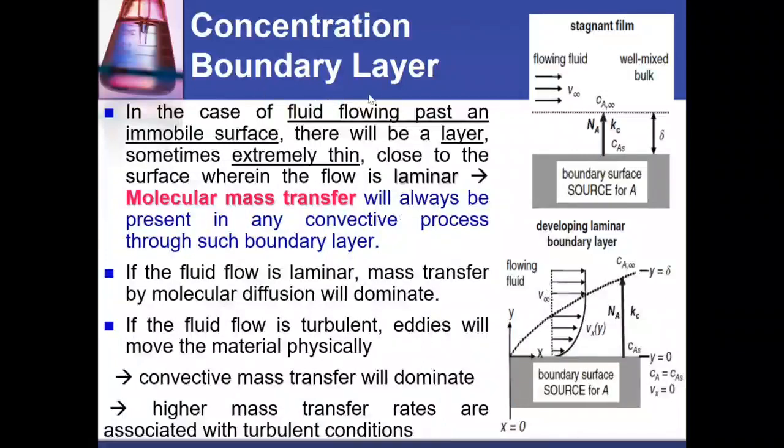So the boundary layer means that when you have solid and fluid in contact, you will have a layer of liquid here that is immobile, same as the surface, and this will affect the movement of all other molecules above them until you reach the center line. In other words, there will be a velocity gradient because of this no slip condition, and you will have a layer like this.